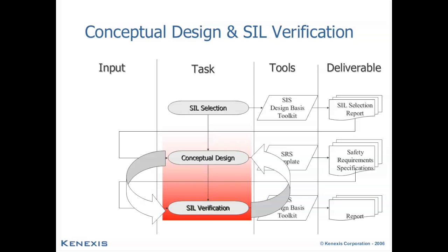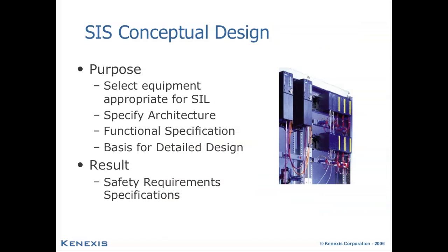In conceptual design, we're making design choices that might impact our ability to meet the SIL target, including selecting the equipment that is appropriate for the SIL that has been selected, specifying an architecture, in some cases a fault-tolerant architecture, to achieve that SIL target, and specifying functional testing that allows us to achieve that SIL target.